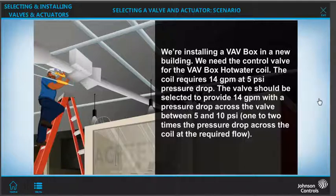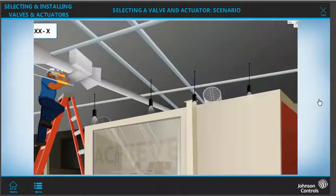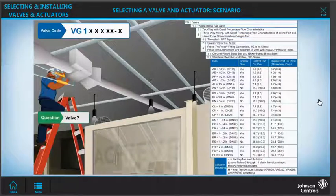The valve should be selected to provide 14 GPM with a pressure drop across the valve, which is between 5 and 10 psi, which is 1 to 2 times the pressure drop across the coil at the required flow. What is the valve? VG, which is the only option.